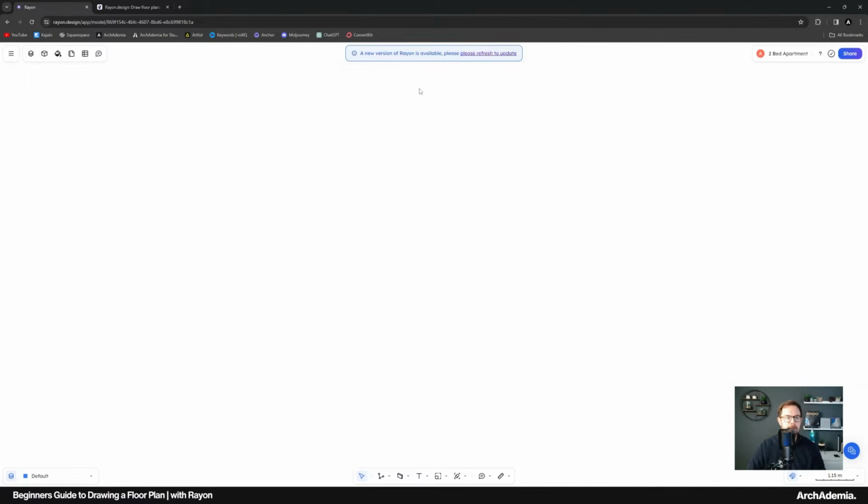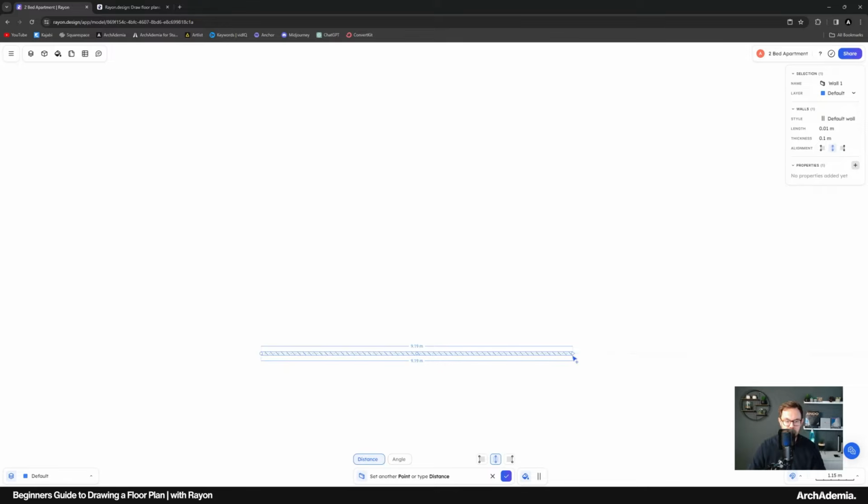It's telling us to update there. Let's just hit that. That was nice and quick. So the first thing I would like to do is start to draw a wall in, and it just says at the bottom, it's very, very clear, by the way, very intuitive. At the bottom here, we've got set first point. So we then want to draw that across. It's currently in meters, so let's just do that. So you hit enter to pick the length, then you can pick the angle, and then click. So let's go 7.